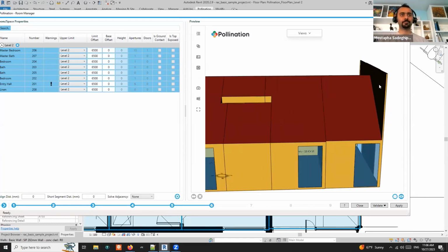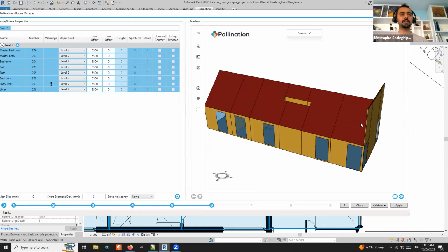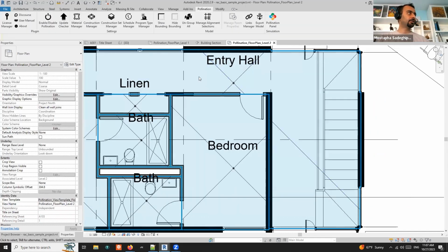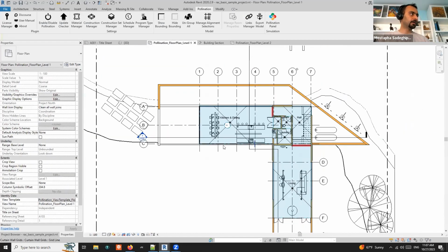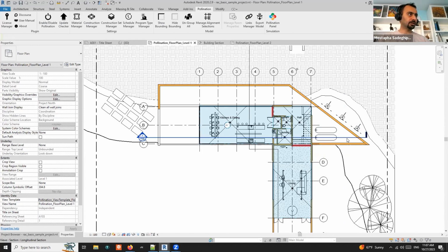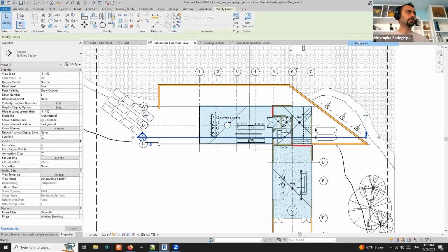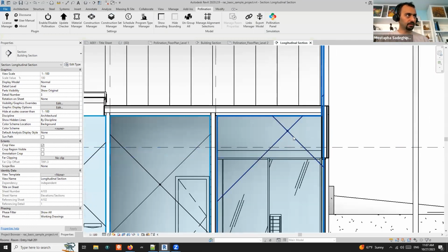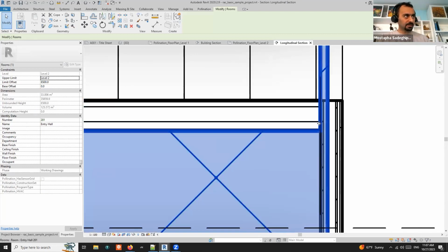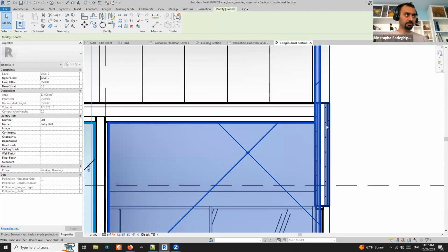There is a leak. And you'll see a lot of these leaks, even for the first floor. If I wouldn't use extruded mode for that living room, there was a leak. There are places where leaks like this happen. If I go to the floor plan and select this section here, go to view, you don't have to do this again, I'm just doing it to show you. You see in Revit, this element stops here, this wall stops here. For some reason, Revit thinks, okay, why would I stop here?